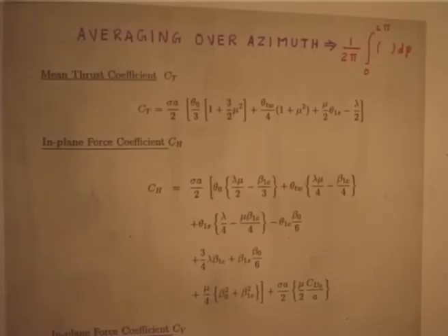If you want to take all the forces, no problem, take everything, then it becomes a little bit more complex. That is why you say let me throw away the rest of the terms and only take tail rotor thrust, that is good enough, which is reasonably a good approximation.